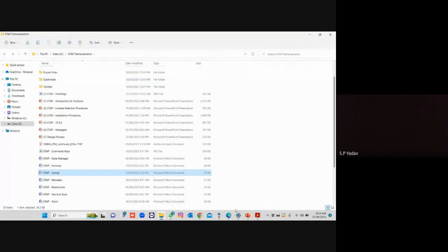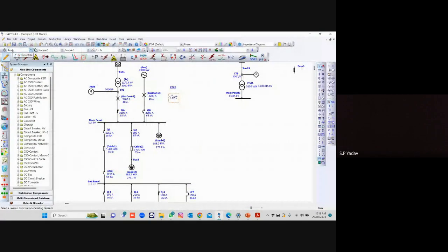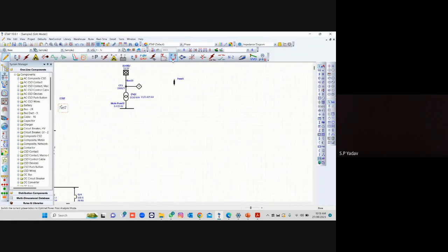Another thing, in ETAP software, by using the database manager you can create unlimited revisions. There are no restrictions. And single line diagrams also, you can create unlimited presentations. With the configuration manager, you can switch off and switch on the sources, for example generator side, transmission side, multiple transformers. You can create any other source configuration by switching on and off. Another advanced feature is auto build. By selecting an element, ETAP software automatically suggests the next component connectivity. It will create a single line diagram automatically, without dragging and placing the elements. It automatically enables the connectivity. So this feature we have.